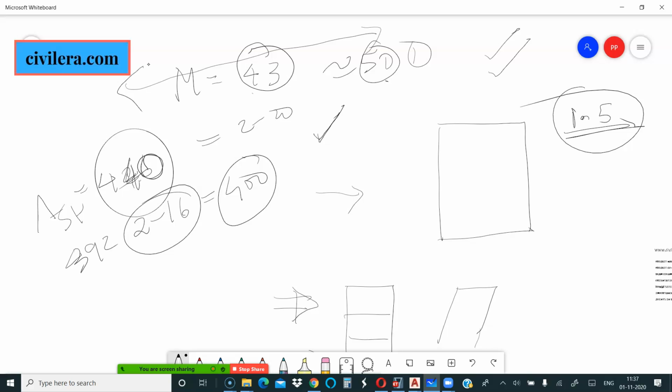And when somebody says it's a library, you should have the presence of mind to ask what library, because many times it may be in the memory of a person, say Jawaharlal Nehru or Patel or whoever. Sometimes they will keep a statue of that person in whose memory it is being built. So you may have to consider that as a load. Sometimes this is not communicated.